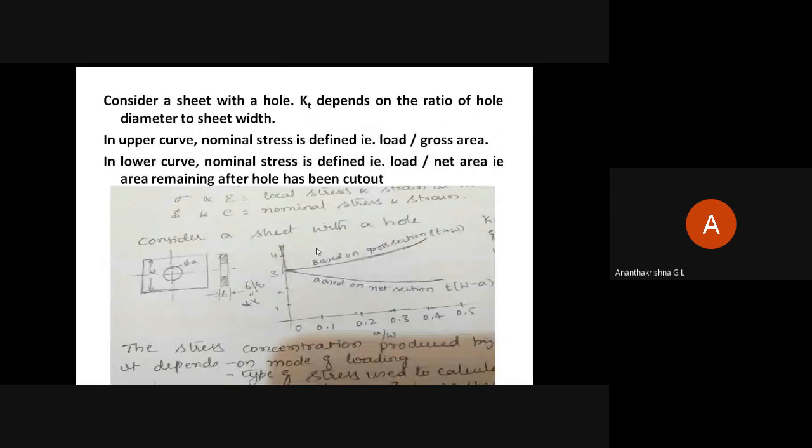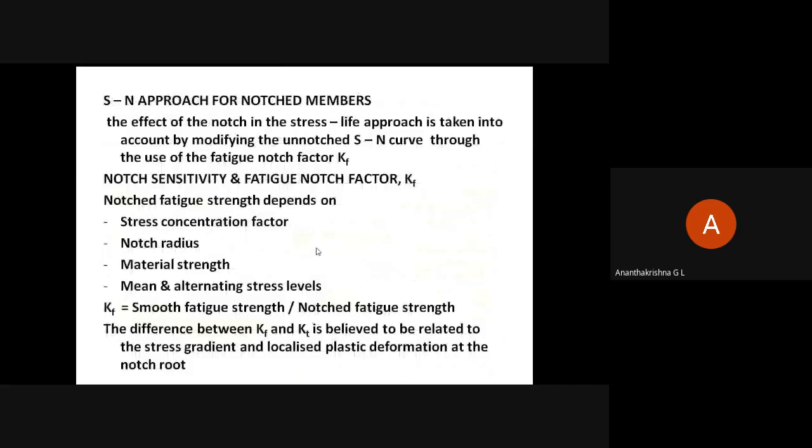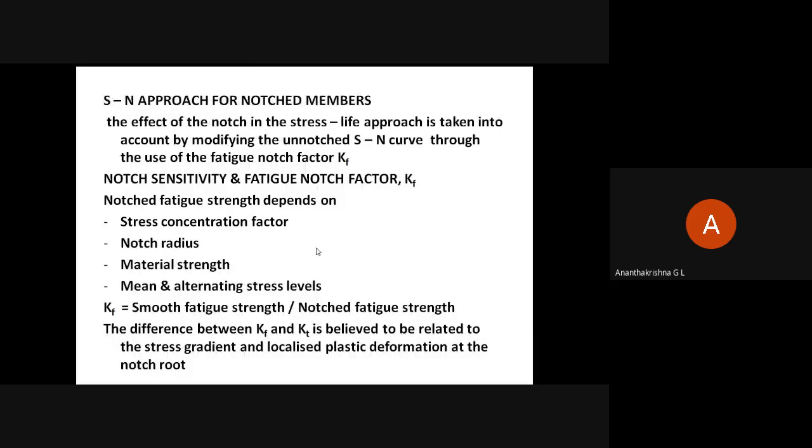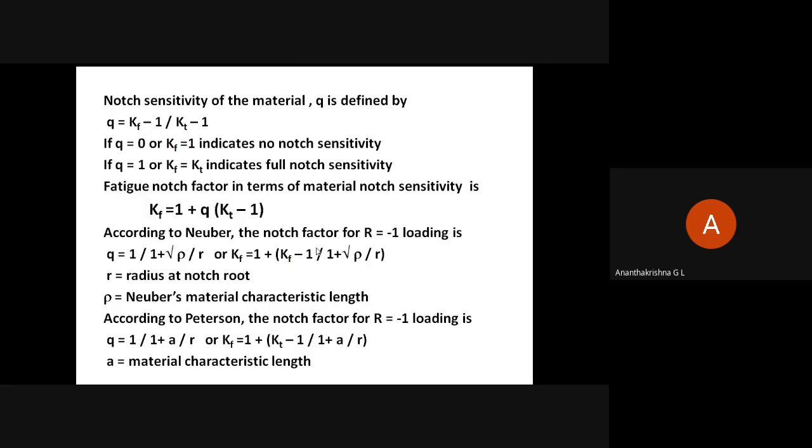Then we learned about the photoelasticity technique of finding the stress concentration factor, in our design lab in seventh semester. And the notch sensitivity factor, we learned in the design for fatigue strength chapter, which is generally given by 1 plus q into Kt minus 1. And mean stress effects, which give us an estimation of long life fatigue strength of parts, is given essentially by the Haigh diagram.